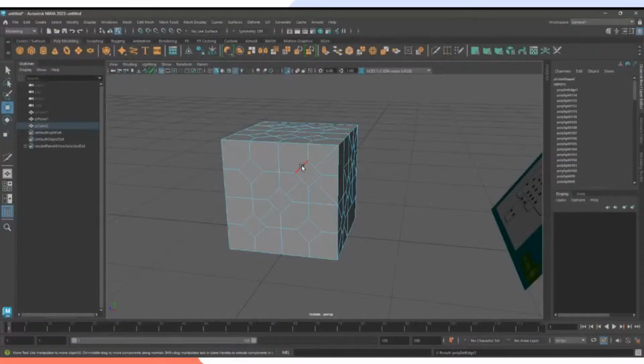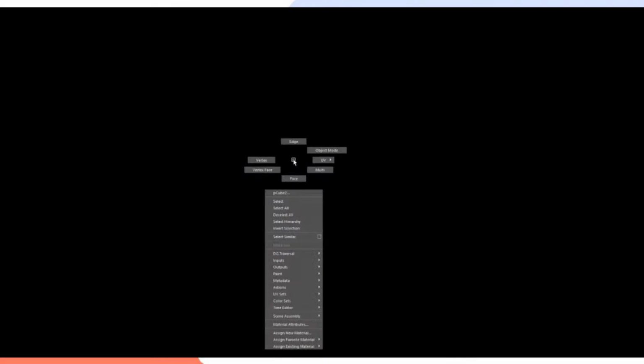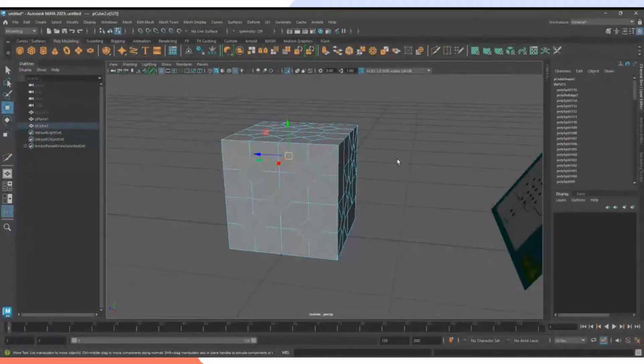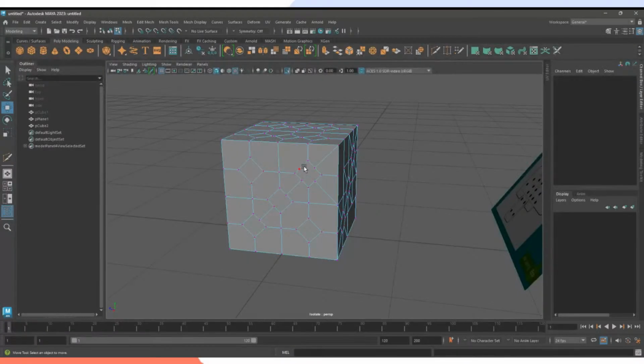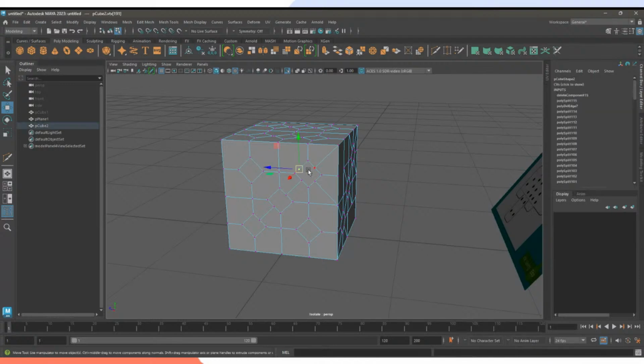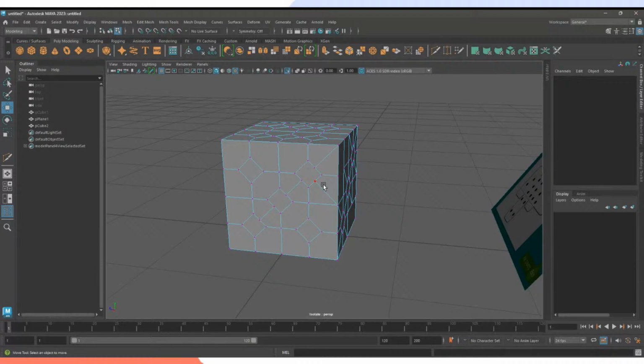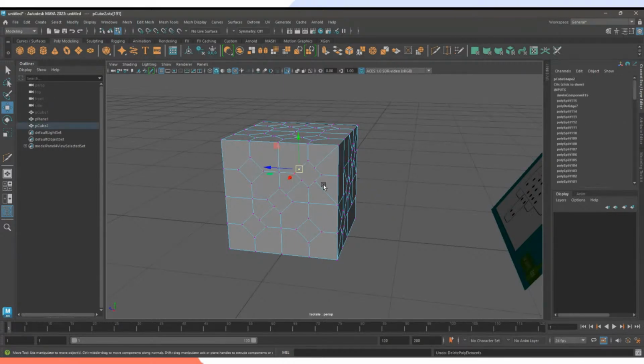Because, for example, if you create that same mistake, for example, here, you only select the edge and then just press backspace, the vertex is still there. And sometimes you don't want that vertex to be there. So if you also delete, it might work. But in other software, for example, 3ds Max, it might just delete the entire face. So you don't want that.